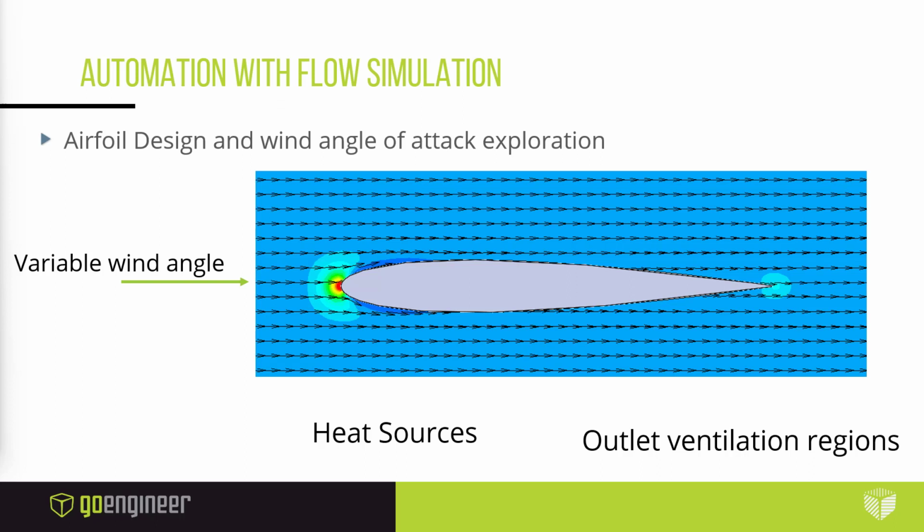When we open up SOLIDWORKS in a moment, we're going to review the flow project setup and learn how to easily use parametric studies to automate the creation of the different flow calculations, so that we can change the airfoil's angle of attack and sort through the output results for comparison and looking at trends. And we'll be able to show how we can do some automated graphs for this. So let's go back to SOLIDWORKS one more time here and step through that example.